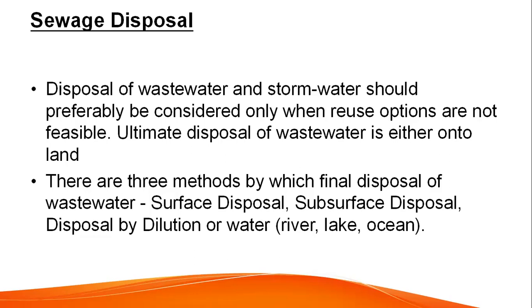The second one is subsurface disposal. By this method, wastewater is introduced into the ground below its surface through pits or tile fields. It is commonly used for disposal of settled wastewater from residences or institutions where there is only a limited volume of wastewater. Little application for large-scale use in municipalities. This was just a verbal description of sewage disposal.